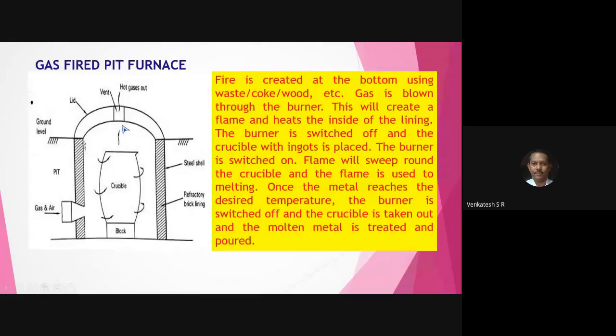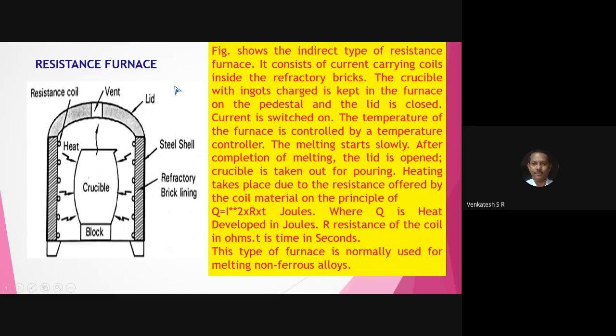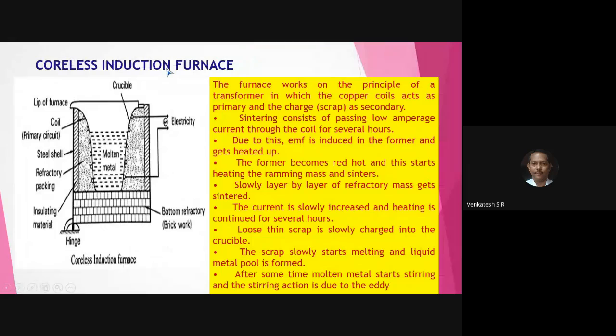Usually, this type of furnace is used in melting of the non-ferrous metal and also sometimes cast iron. Next, resistance furnace. This is the commonly used furnace in steel foundry and non-ferrous foundry.